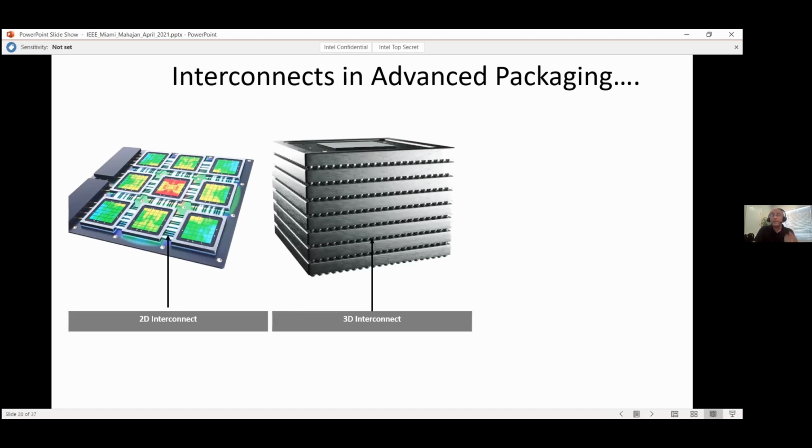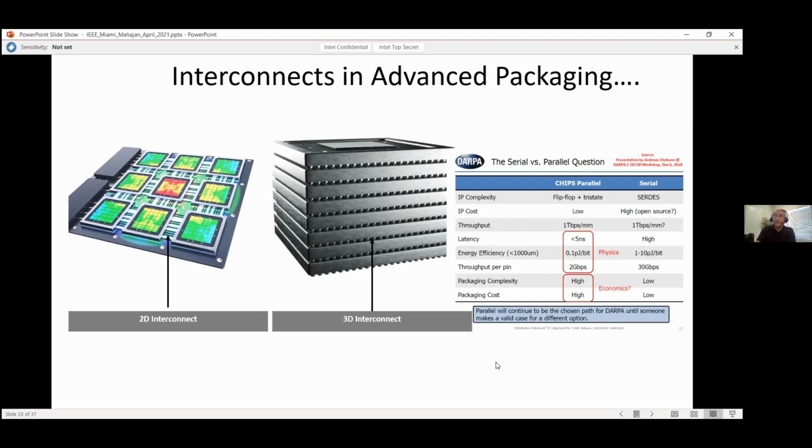Or do you build multiple lanes and allow things to move slowly, but the aggregate of what moves along is still high and you get high bandwidth? That's called the wide and slow approach or the parallel approach. If you compare the parallel approach to the serial approach, the parallel approach sends signals with less latency. It also sends signals across more efficiently.